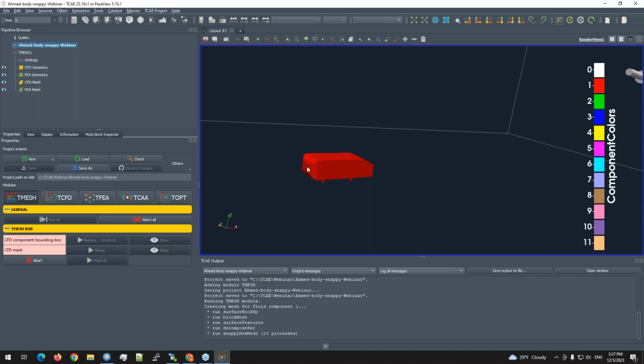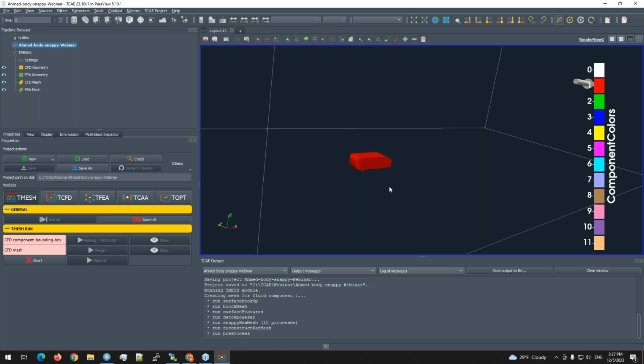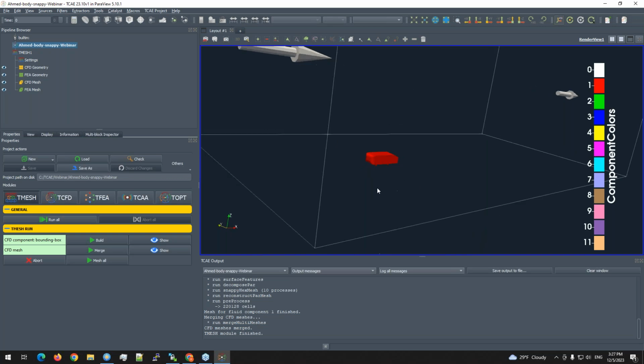Typically, you need to check if all your object parts are meshed properly, and of course then if the refinement is enough to get accurate results. And typically when we start a new project, we do some kind of rough mesh which nicely describes your object and for which the simulation runs well, and then we can go for the refinement and finer meshing setup, and basically we are comparing to the previous results to see the convergence to the real physical, let's say, or measured values of your object.